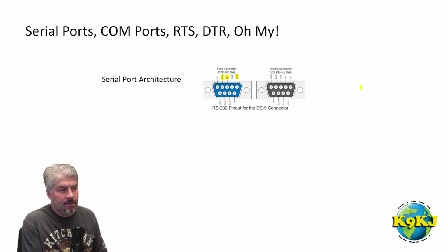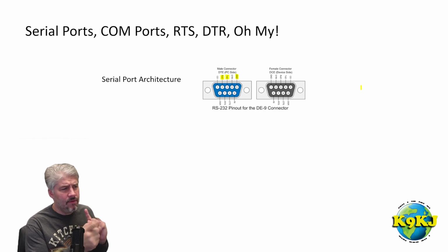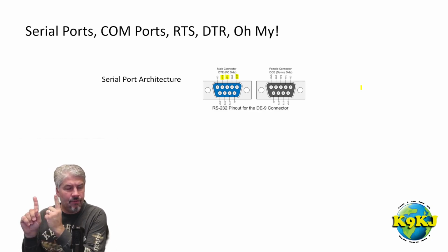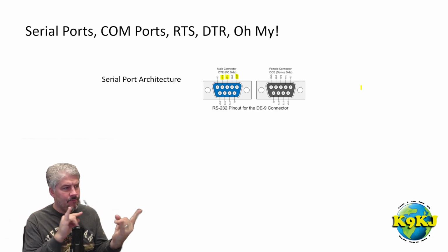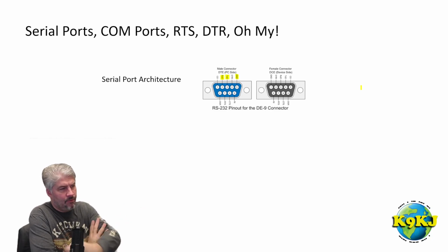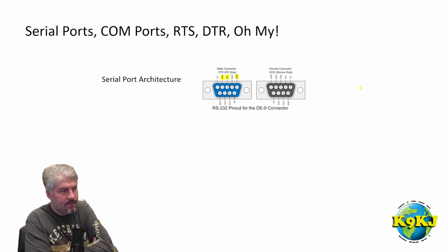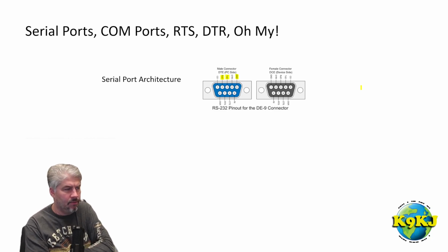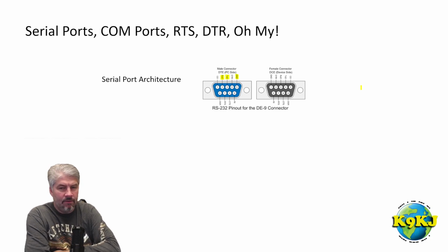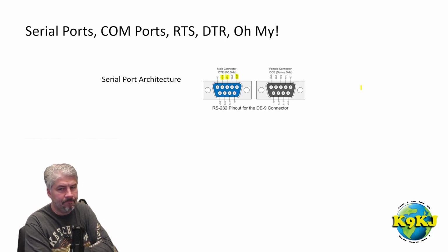To enable communications, there's a transmit pin and a receive pin, and on the other end you would swap the transmit and receive so that you would have two-way communications. That's all you would really need for bits to be communicating between two machines, or maybe a communications piece of equipment, and what they would call a terminal or a computer.